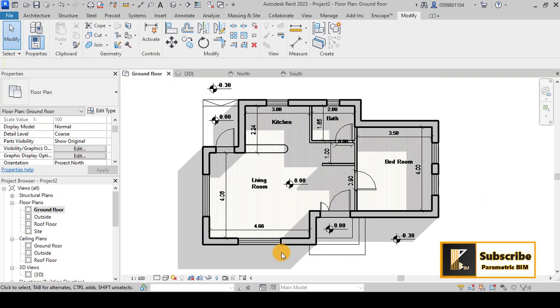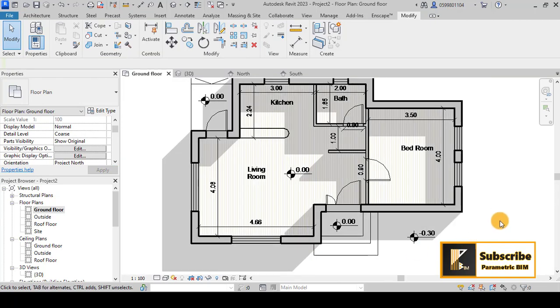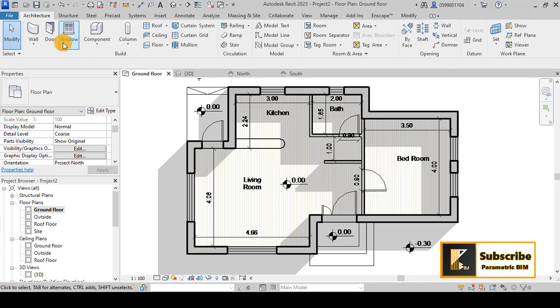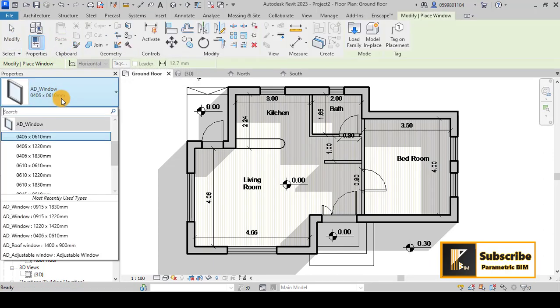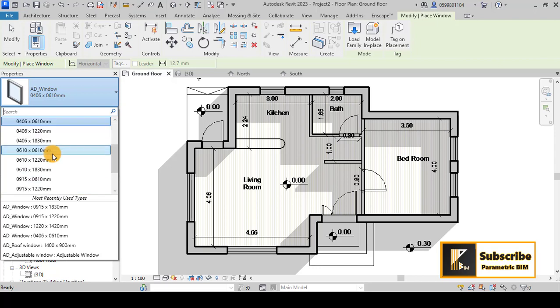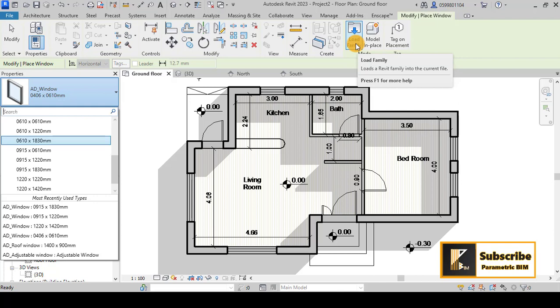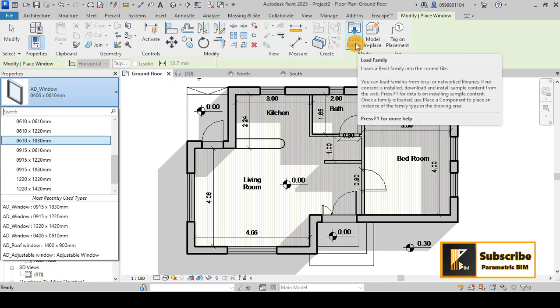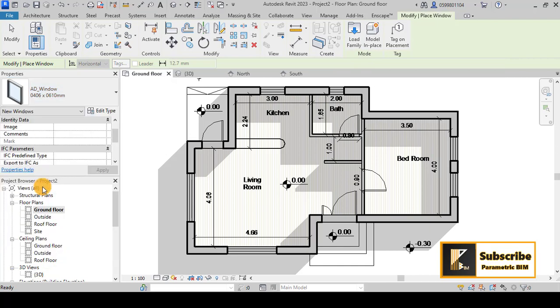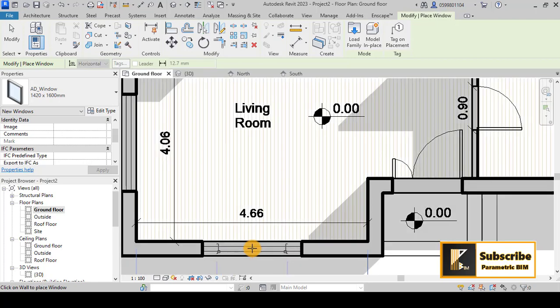And also now it's time to add the windows and the doors for the plan. So simply you can go to architecture and then you go to windows. So you will have some families about windows that you can choose and use in your project. But if you are not interested, you can go and load family from the libraries of Revit. But I will choose any one now and modify it after that for this tutorial.